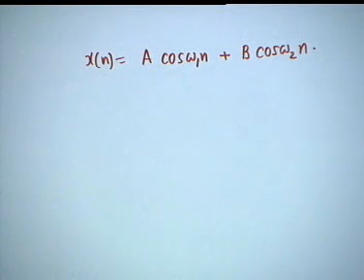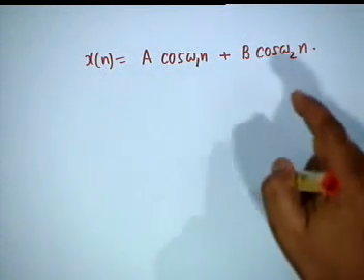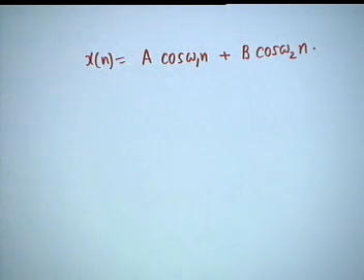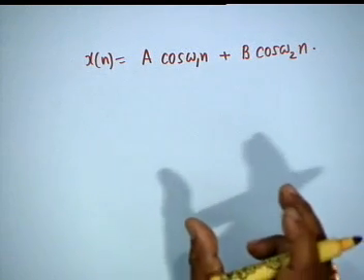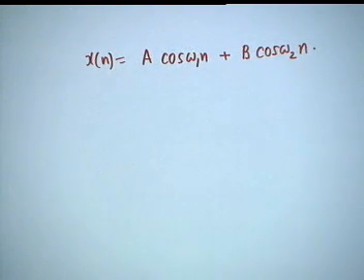Is that correct? It is not. A digital signal, even if it is a sine or cosine representation, is not necessarily periodic. For periodicity, omega 1 by 2 pi must be a rational number. Similarly, omega 2 by 2 pi must be a rational number, and if they are periodic, then the periodicity of the sum is the LCM. Okay, you know how to do this.